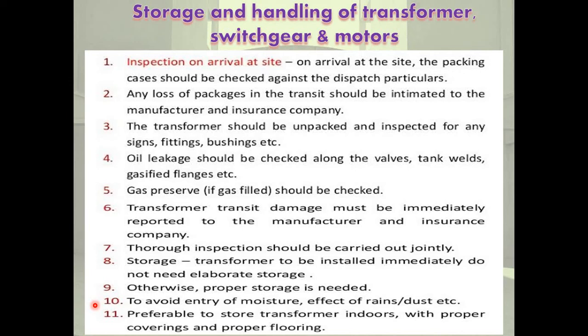The basic requirements of the machine's foundations are horizontal level, rigidity, and freedom from vibrations. While storage and handling of all electrical equipment, the procedure of receiving electric machines at site is also very important. The machines are inspected and packed in the factory before dispatch. On arrival at site, the packing is inspected for transit breakage. If any, the packing is unpacked. All the parts and accessories are inspected to see if the material received is as per the dispatch list. Also, the inspection reveals transit damage.